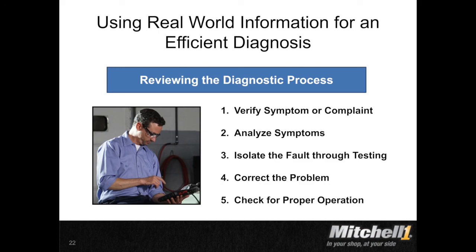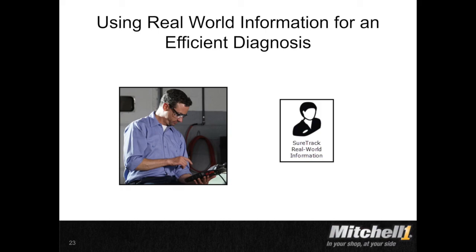And then you move on to correcting the problem, and that's where you go back into your repair information source to look at the OEM information about repairing that component. And then finally, you want to check for proper operation just to make sure that you've done everything right and completed the job. So, yeah, using a real-world information source like SureTrack is a great way to reduce diagnostic time and to have more confidence when building out and carrying out your diagnostic strategy.